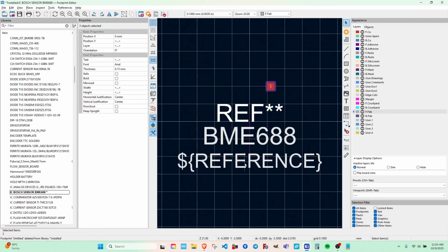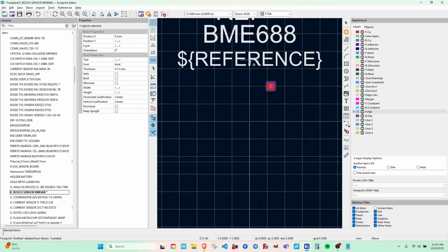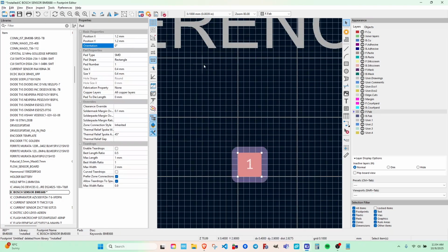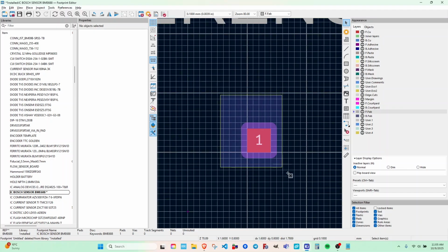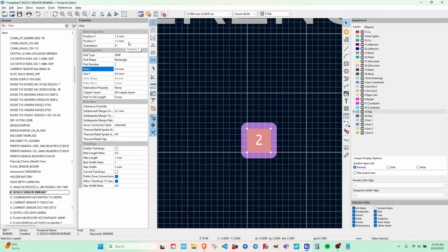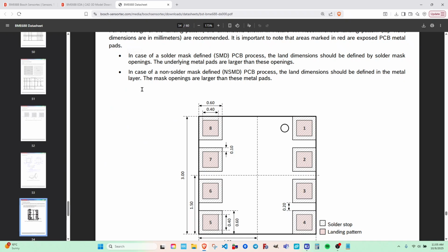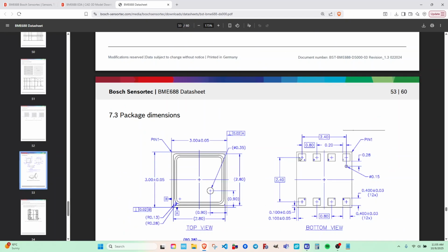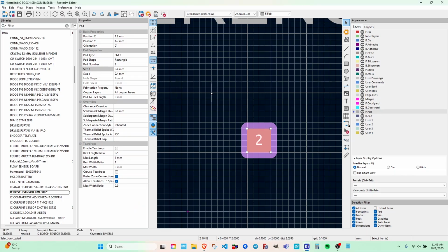And we can move these out of the way for now until we're done. So this guy will say he's 1.2 and 1.2. Okay. Now, if I copy and paste him, and I'll put him directly on, and I'll change his number to 2, and I will move him down by 0.4 millimeters, because remember the pitch? Sorry, excuse me, 0.8 millimeters. 0.8.